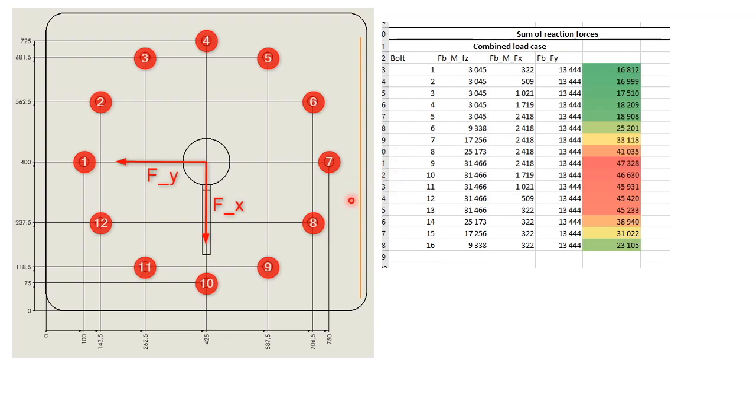These two images are not connected here. There was an example with 60 bolts, but the principle is still the same. Even if you have a force that is pulling towards you, you can also calculate that as a normal force if it is evenly distributed, and also add it to the calculation. Remember, what we have calculated now is only reaction forces. If any of these bolts are pre-tensioned, as they might be, that will of course come in addition.